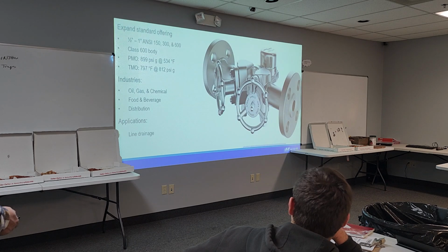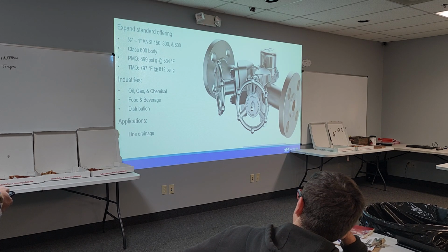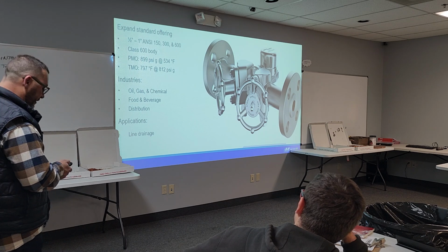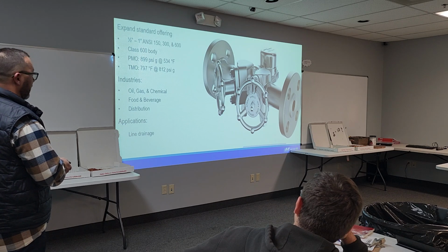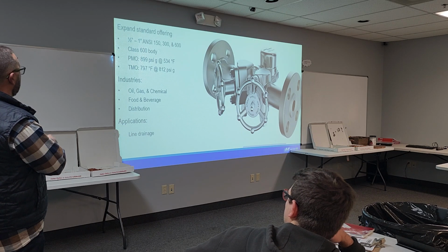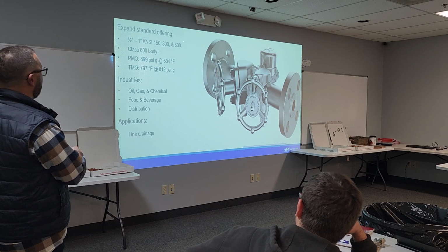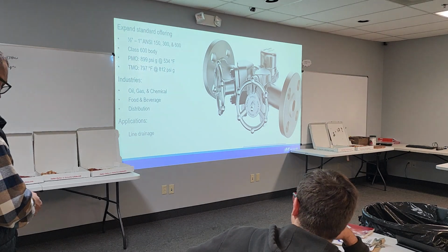So they just recently came out with these where they're flanged. So for heavier, higher pressure and greater capacity. So that's a brand new product. It's pretty good and all stainless. They still only go to 1 inch, but they're 150, 300, and 600 pound class with the raised face flanges.